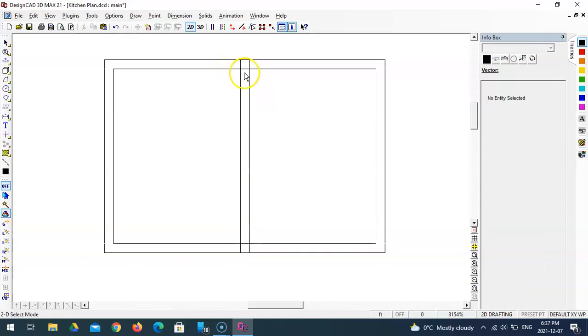And what I want to do here is break this before I trim it. So to do that, I'm going to press the letter D. And when I press the letter D, I get the section trim. So I can draw a little box right here by just, you can see I can drag it. I can even do the whole thing because I want to get rid of both sides. And now that it's broken, I can now use that same trim tool that I used before, that's that second one in, to trim here and here, here and here, as well as the bottom.